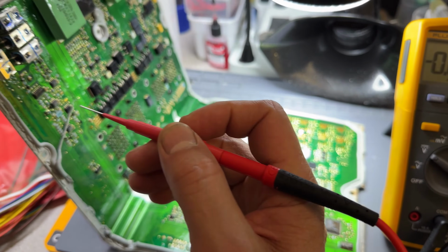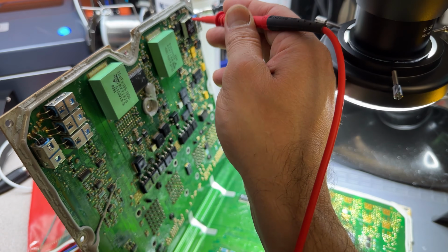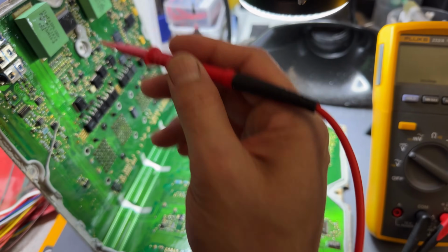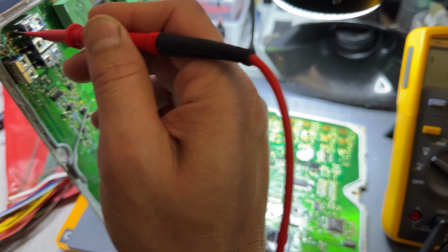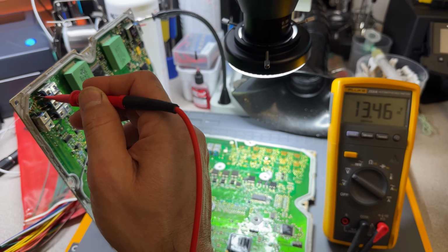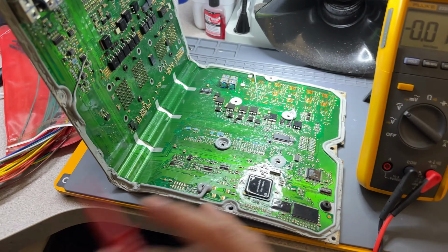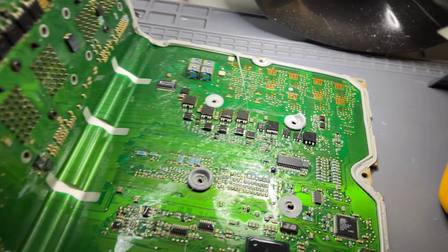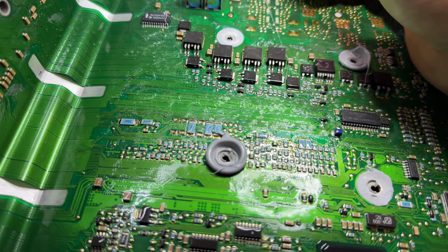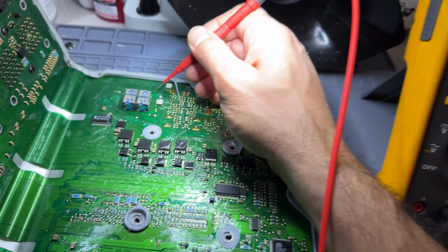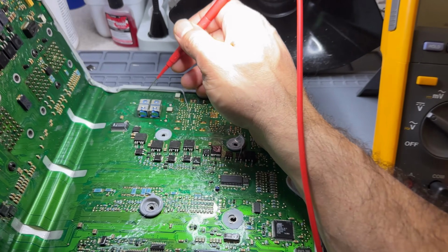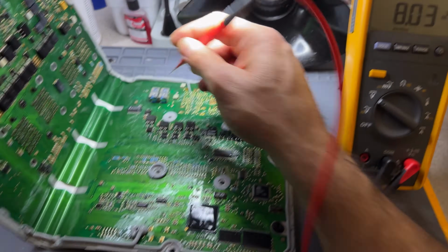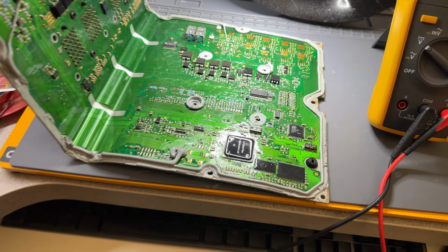I don't want to damage the computer. This coil should have 13 volts in here. All of that upper side is 13 volts. All these caps should be battery voltage, and they are all alive. Believe me, I did all this checking and everything is good. This should be also on. Let me just see. Yeah, so we got battery voltage, and I want to check the other side too. And we got battery voltage. So as you can see, everything is powering up.